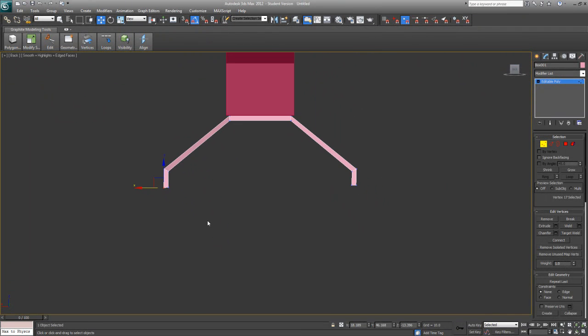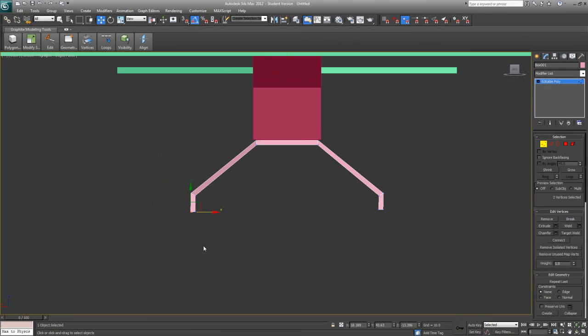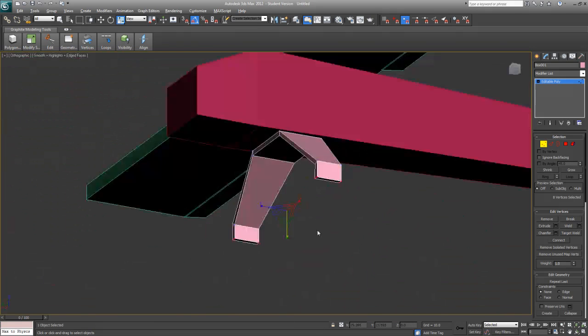But if I box select, I'll select them both. I could lift this up and try to even it out by eye, but I can box select all of these, and while I'm at it, I'll select these over here too. Use this scale tool. Let's just roll that in the Y, and what that does is scales everything nice and flat together.